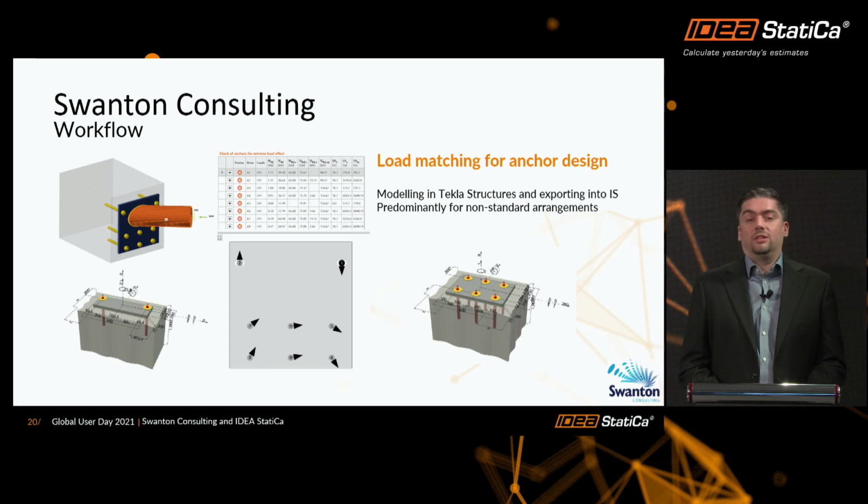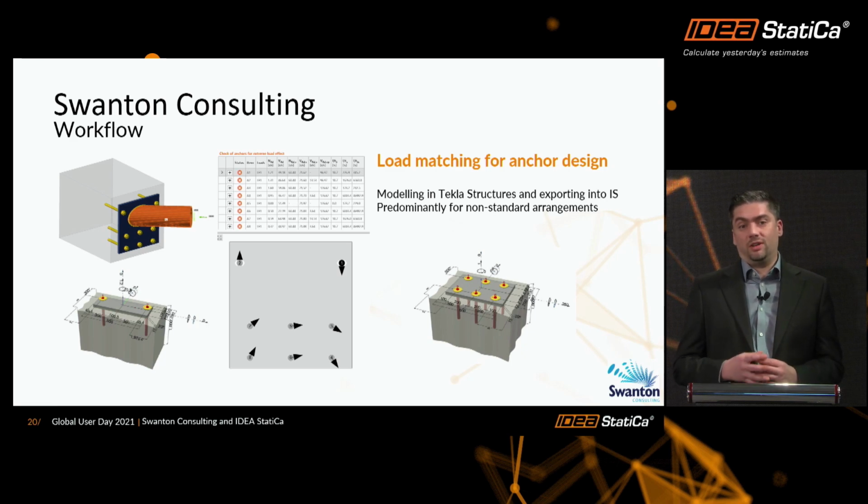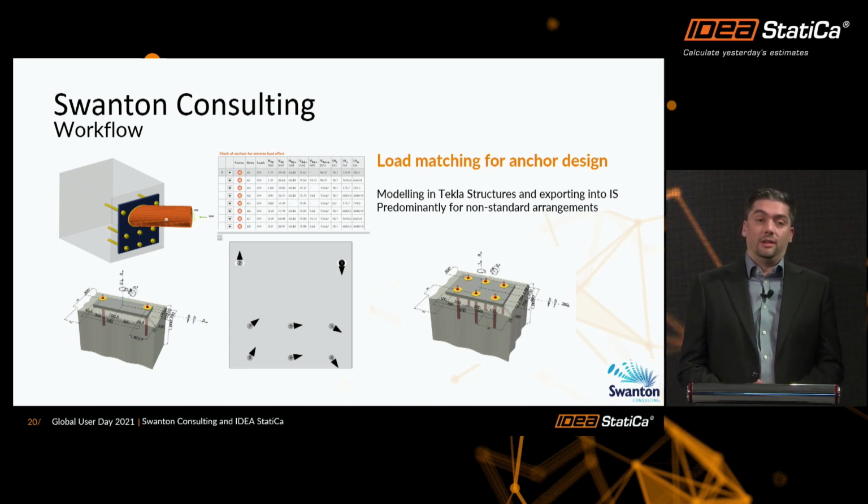Load matching for anchor design. So we are utilizing IDEA StatiCa's capabilities of flexible base plate design and flexible base plate checking, where we are accounting for prying forces and deformations of concrete and steel. And with the forces we obtain from IDEA StatiCa, we do a load matching design in, let's say, Hilti Profis to check for the actual anchor capacities with all the edge distances, and sometimes we take it even further into verifying these connections with additional reinforcement.